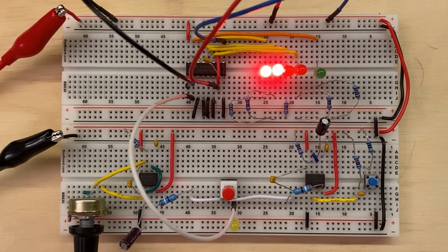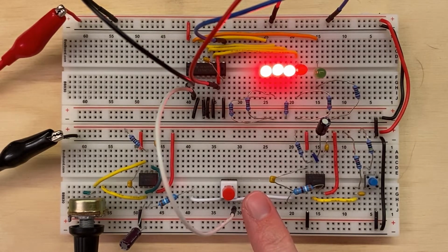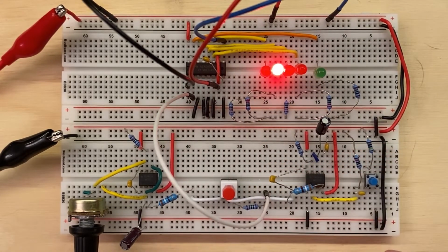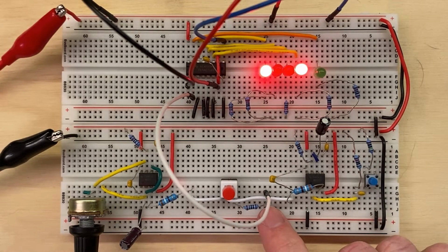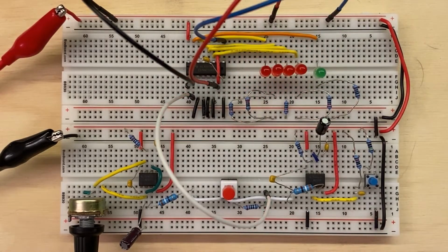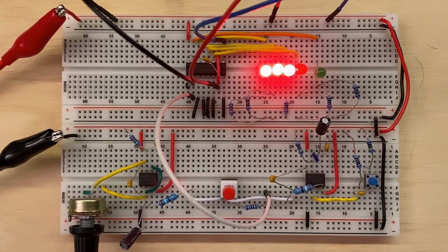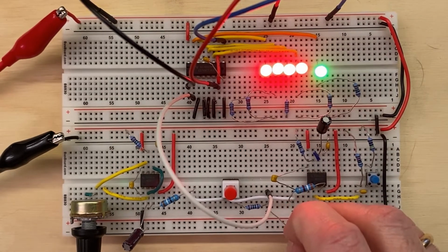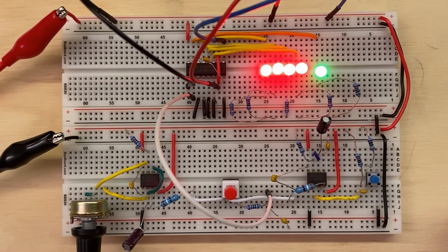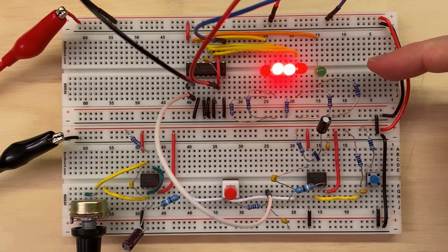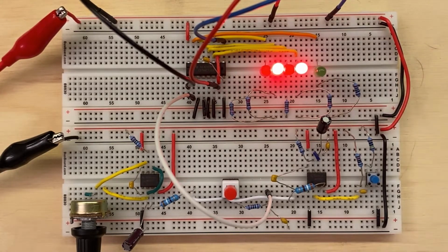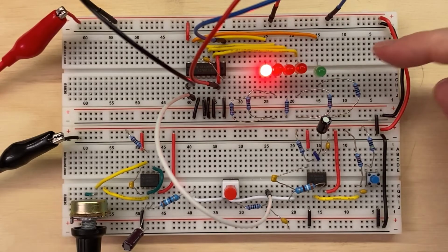Now, as we go along in our project, we're always going to want to take special care of this clock signal. So I've added a little 1 kilo ohm resistor here, and I'll put the clock on this side. And so it's working fine because the kilo ohm resistor isn't going anywhere. So it's just like a wire. However, if I add a capacitor to it, you'll see that it acts kind of erratically. You see, it's not really counting correctly. It's kind of doing whatever it wants, really. And what we've done here is just put a low pass filter, and basically now our positive edge is not so straight. And that's what kind of messes up the count here.